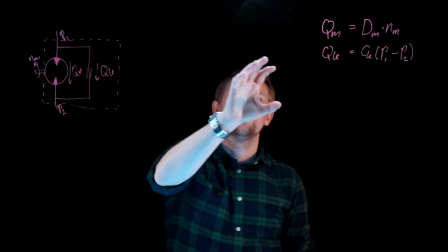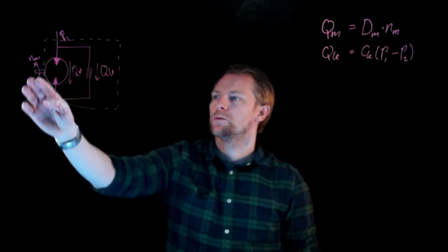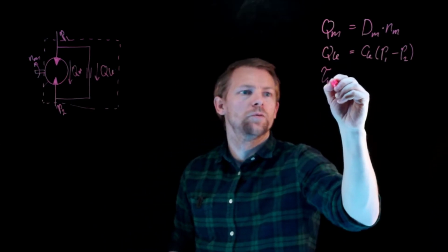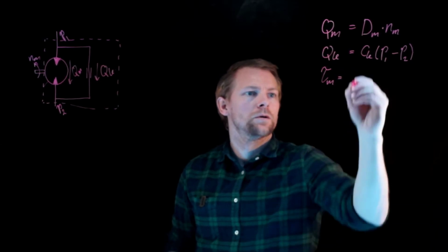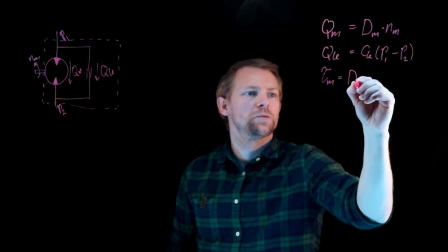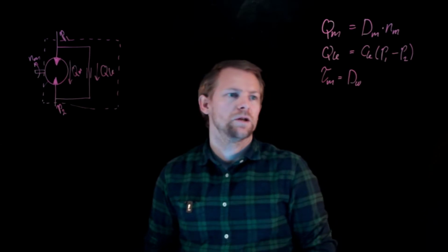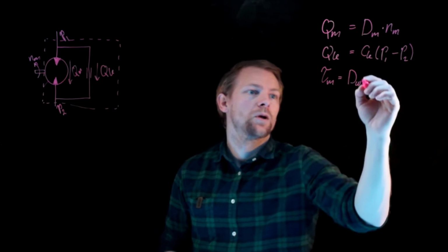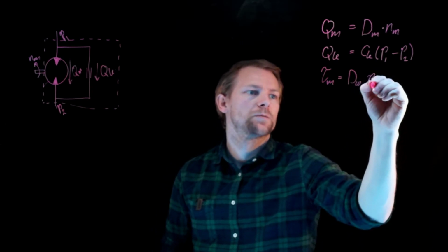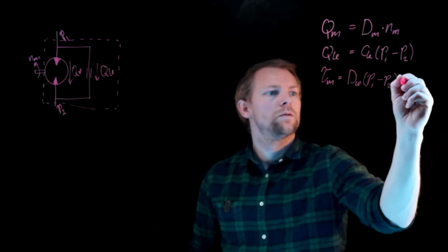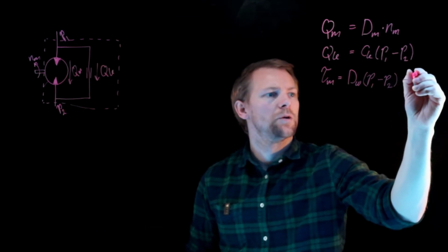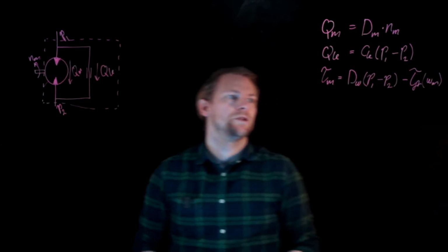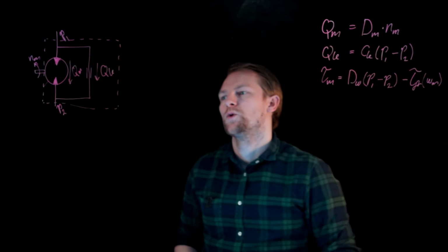So now, what is the torque that the motor will deliver out here? Well, the torque of the motor, we have the displacement where we remember to have it in the SI units. So it needs to be cubic meters per radian. And then we multiply that with the pressure difference. We can include some friction term, which is here said to be dependent on the motor velocity.